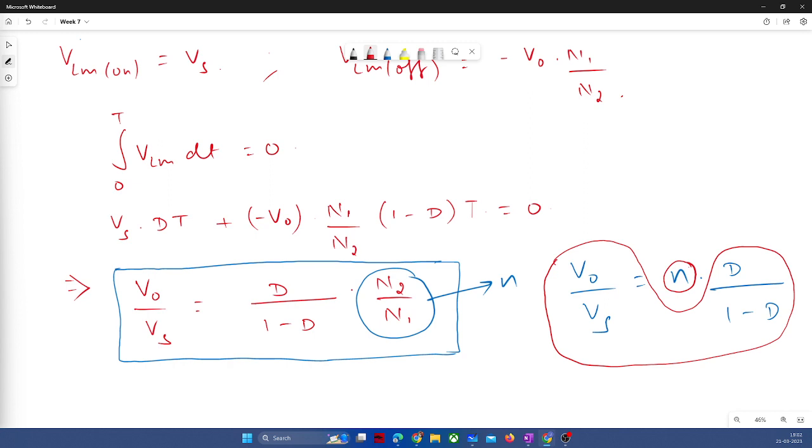So with DCM, you are able to design a good power electronics converter. Which transformer is size-wise bigger or smaller, CCM or DCM, for the same output rating? That we will have to solve with given design parameters, because once you keep the frequency fixed, the size of the transformer will be fixed. So for that purpose, we will need to compute the frequency, and it will depend on the converter.